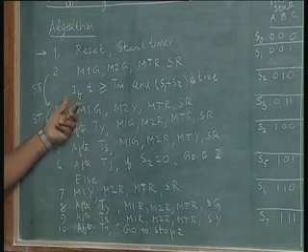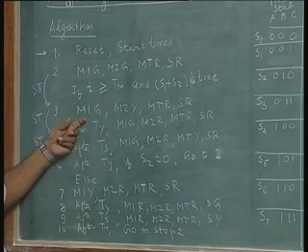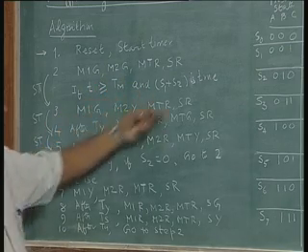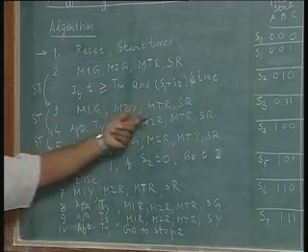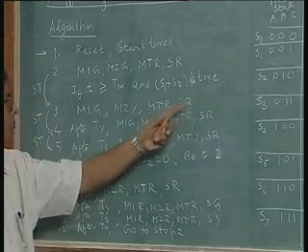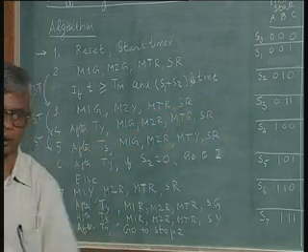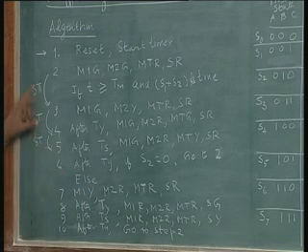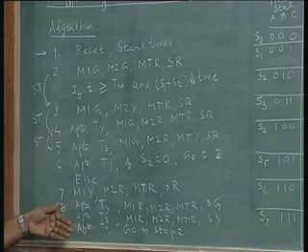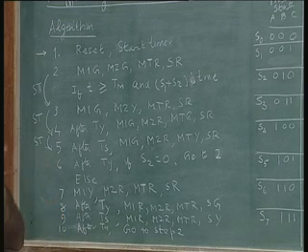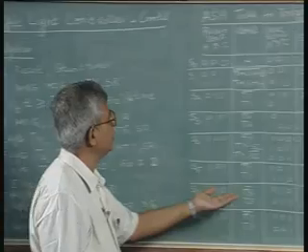So what I should really say is, if T is greater than Tm and S1 is true, start timer and go to M1G, like that. Similarly, I say M1G, M2Y, MTR, SR, and after Ty, etc., start timer. So start timer should be put in each stage, which is assumed. This is just to recapitulate the ASM, because it looks a little complex. And now, with this background, I want you to look at the table. This is the ASM table.